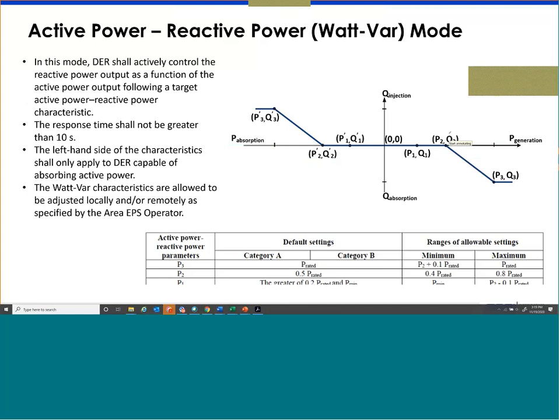So up to this power generation level, from 0 up to say 40%, 50%, there is no need to provide any reactive power support. The idea is that you are not causing any voltage problem, so I don't need any reactive power from the DR. Above that level, if you remember the first example that I showed in the morning, above 50% that plant was causing overvoltage. In those scenarios, the more power you generate, the higher the voltage goes, so you need more reactive power to push the voltage down.